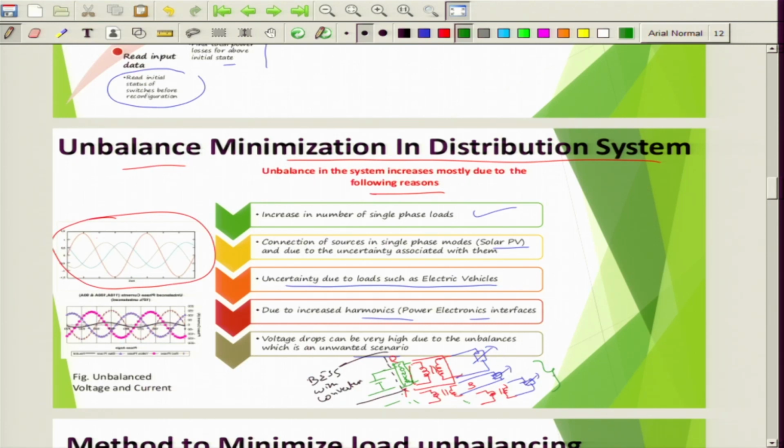So what we can do is use the battery converter of R phase, because you have to balance the system. If sufficient SOC limits are not crossed, then you can charge the battery connected to R phase, so that you bring the R phase loading equal to Y and B phase.